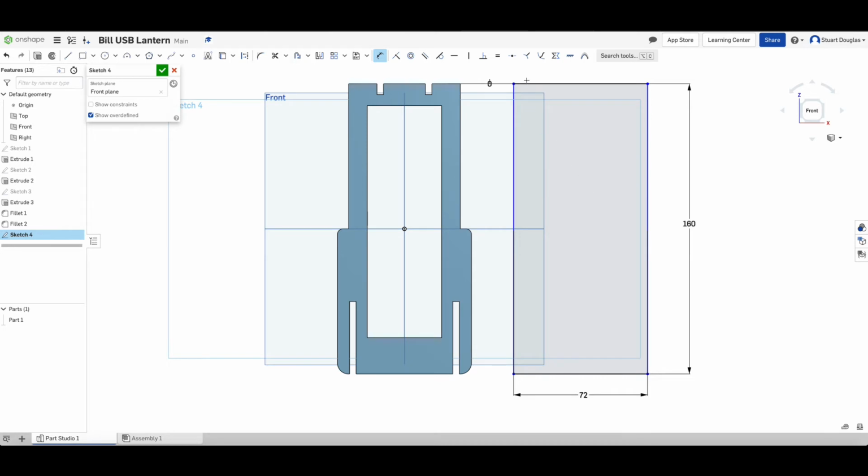What I now need to do is go and draw a second rectangle on the corner here. I'm going to drag this rectangle down. This rectangle needs to be 80 in depth, and because we made this one in the middle, it's snapping to that line. So that helps us. I'm going to select once. I'm going to do one on the opposite side. And notice now I drag down, again it's snapping to that distance.